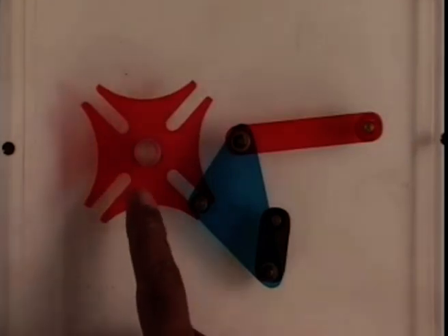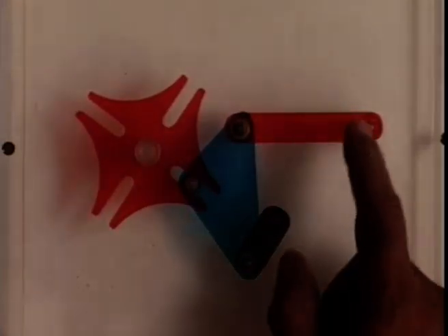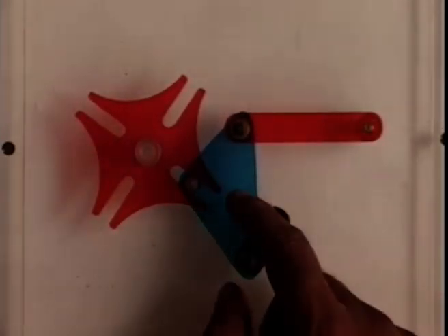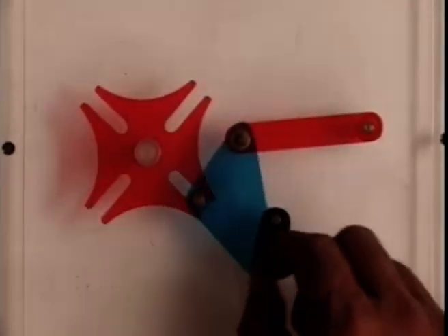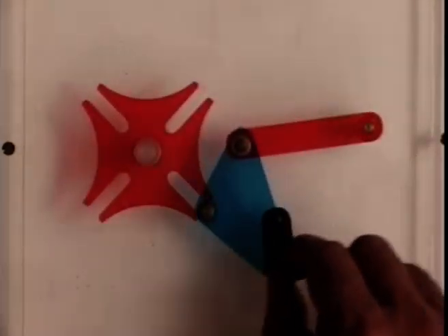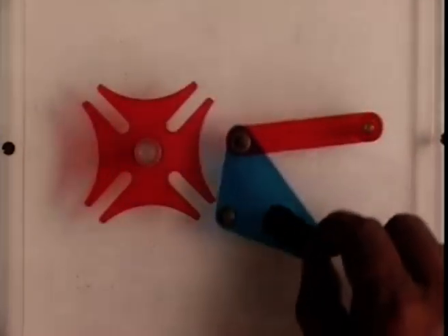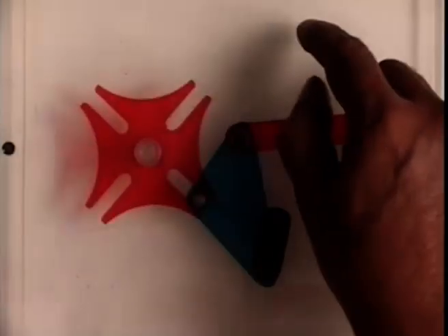We can drive this Geneva wheel by this coupler point of this 4R linkage. As we see, this is link 2, link 3 and link 4, and this is the coupler point. So if the input is given to the crank of this crank rocker linkage, then this particular coupler point gets into this slot and goes out of the next slot.